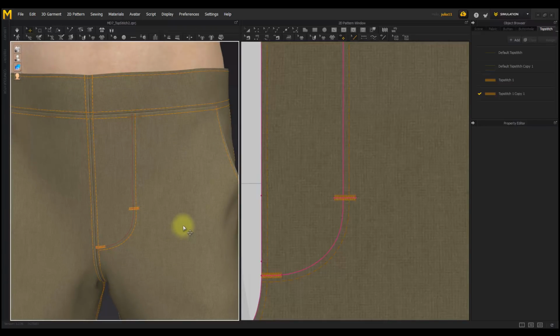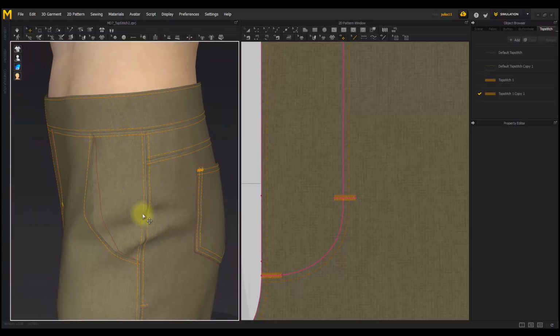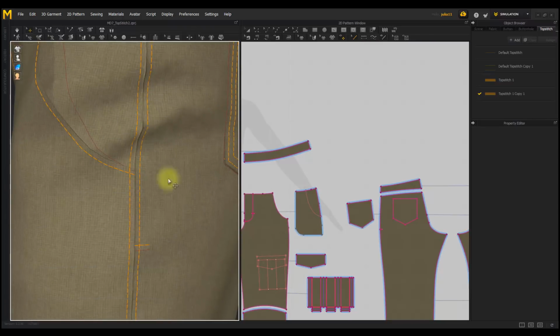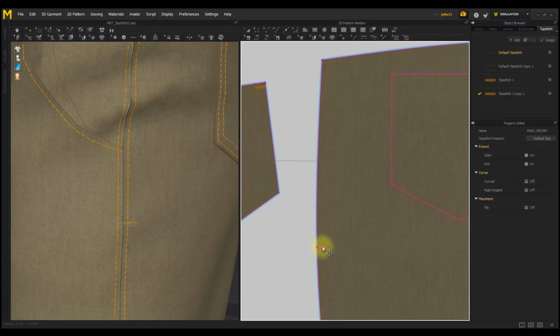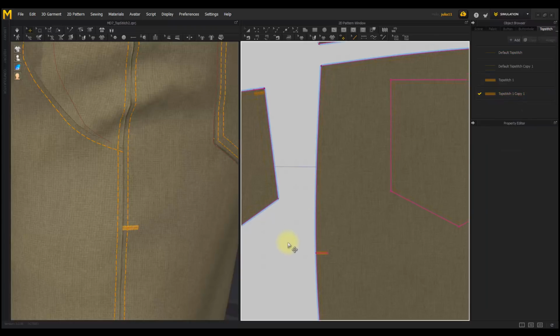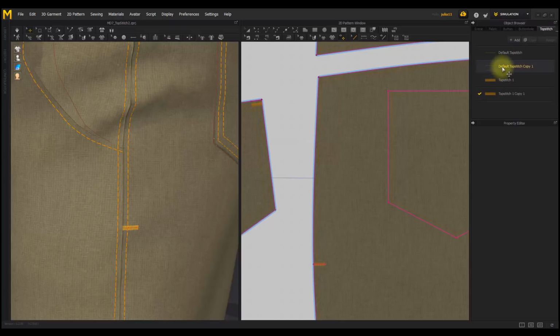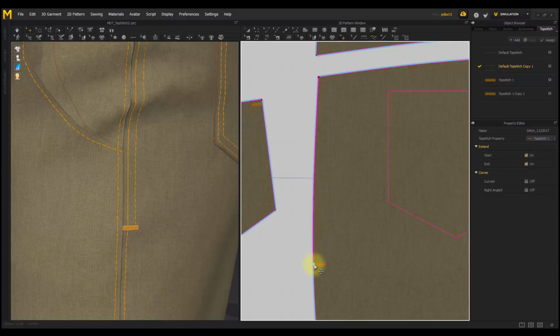Now, let's make bar tack stitches and reinforcement stitches on the sidelines. Select the stitch that is created in the internal line segment of the sideline and assign it to the bar tack stitch by pressing the Assign button. To create a reinforcement stitch, select the existing 2-line stitch item, then use the Free Topstitch tool to create a stitch in the sideline.